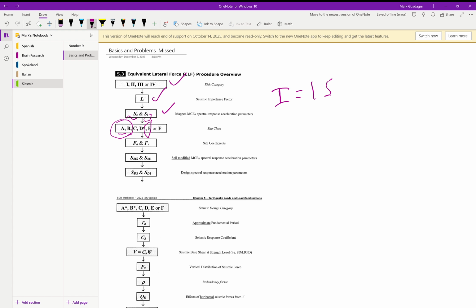And so where this becomes important is how much of that force gets transferred to your building is a function of at least 4 different things. First, it's a function of how much the ground's going to shake, but then it's a function of how stiff your ground is. And taking these 2 parameters, that's where you would get your SDS, which is shown here.